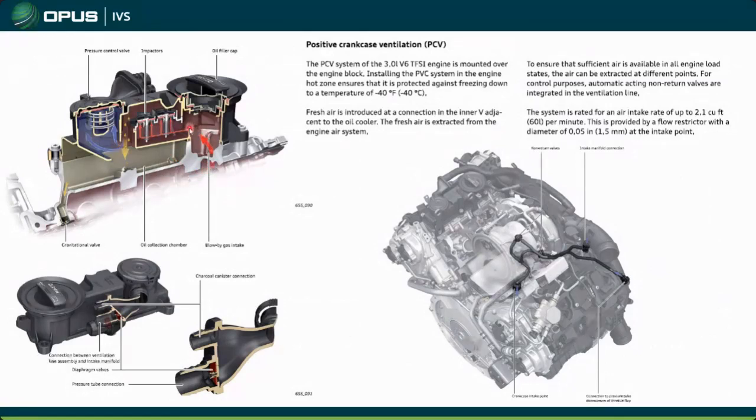The blow-by gases come up in here, and they hit what they call an impactor. Now, this is kind of replaced in a lot of ways on these systems by cyclonic action. What happens here is it's almost like a little filter screen kind of thing, that as the blow-by gases with the oil come through it, those screens force the oil droplets to come together and form bigger droplets from very small atomized droplets.